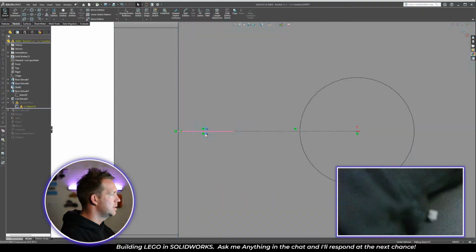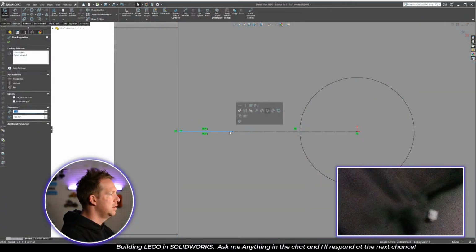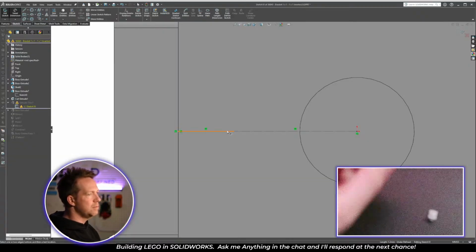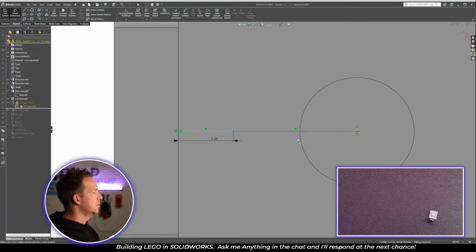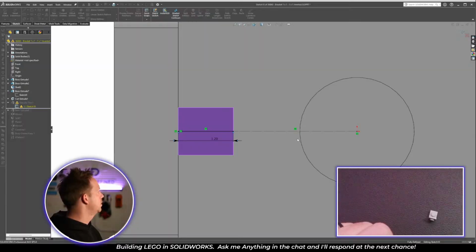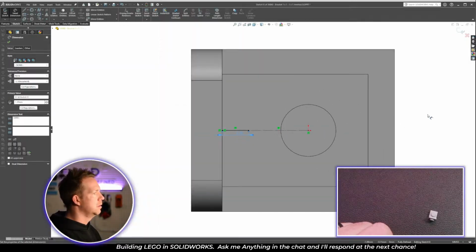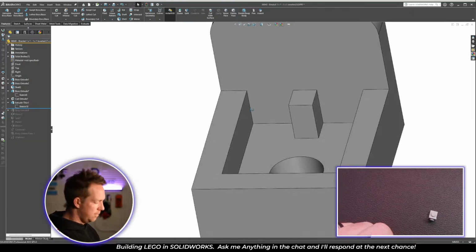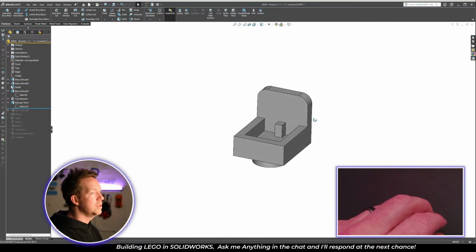And I can tell that because it says equal, equal, and horizontal, horizontal. That's a sign that there's a double line there. So delete one, it removes them. Put the dimension in. Press OK. Save. Now all that detail is looking really good for this part.